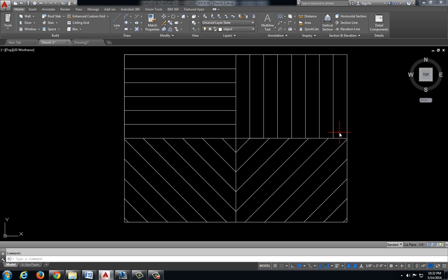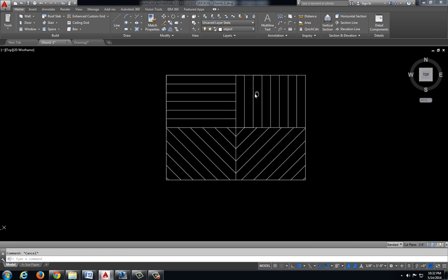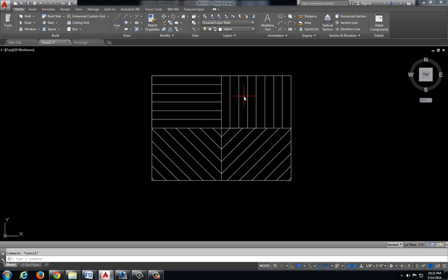Not only do we want to print it out, we want to print it out to scale, meaning this top line here, I drew this top line as 8 inches. When I print it out, I want the printout to be 8 inches. I want this line to be 8 inches on the printout itself. And that's one of the big features in AutoCAD, is printing objects or machine parts, architectural drawings to scale. So then you could, let's say, draw up a set of house plans, give them to the framers. The framers can then frame up the house, or they could put their architect scale on it and figure out the correct measurement for different walls.